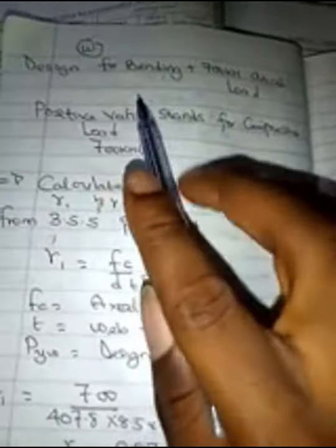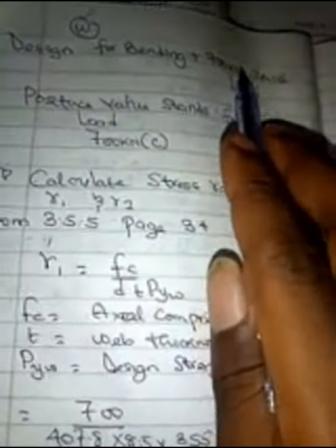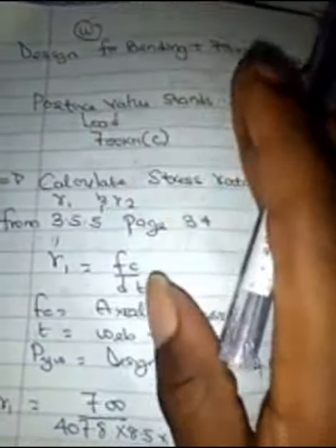For the next condition, we are designing for the bending and the 700 kilonewton axial load. You know, we are given 3 questions, and I already explained to you that your chart actually explains this. Neutral axis at mid depth, this one, the rule generally is for the bending plus load. This neutral axis at mid depth is for bending only. Then axial compression is for axial load only.